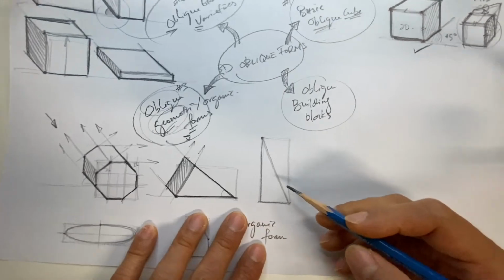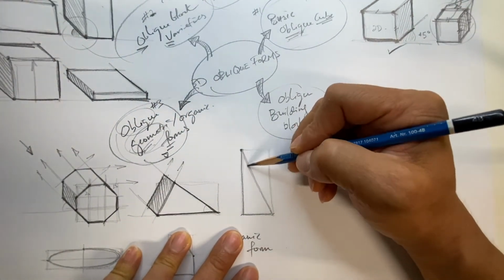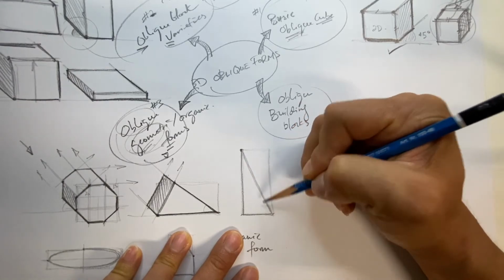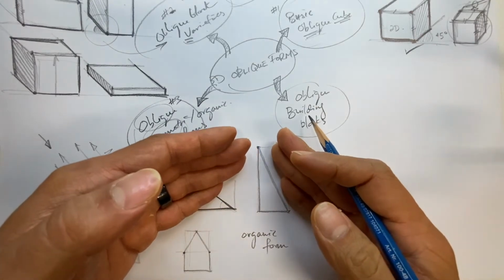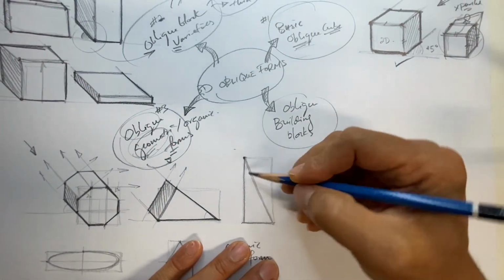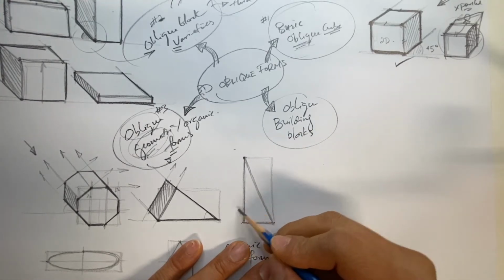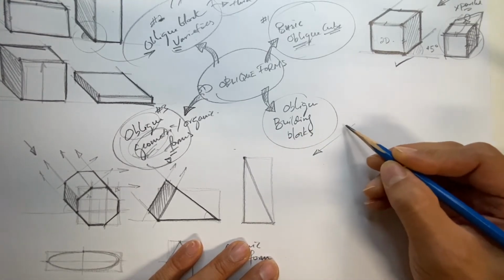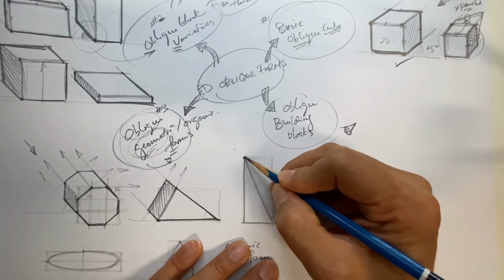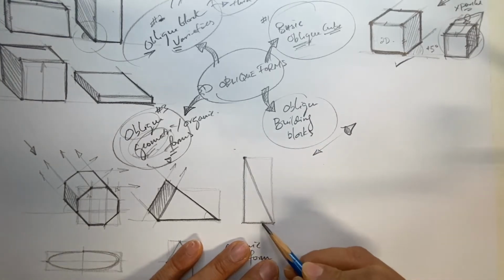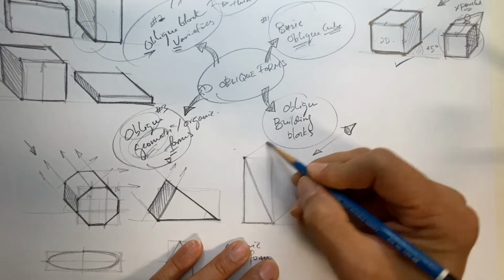Okay, so how about this? Let's project this from the right. Why so? Because I have the slope on the right, and if I project it to the left, I will not be able to see the full effect of the slope. So in this case, because the slope is on the right hand side, I want to see the face of the slope. So I'm going to look at it from the right this time. I'm going to put my eye here and look at it from the right. So it will make sense for me to project this line from the horizontal at 45 degrees to the right. This one to the right.